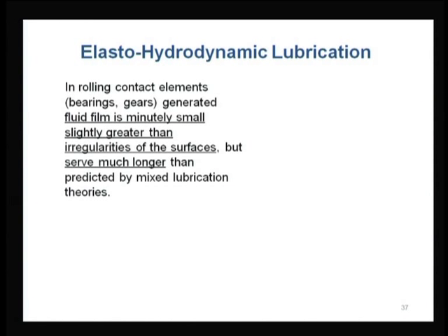And whatever simple theoretical analysis we do, we get a film thickness of much lesser magnitude, but in the actual case, when we do experiments, we find the film thickness is on the greater side. Theoretically we are not able to get the results if we go ahead with the simple hydrodynamic lubrication mechanism.